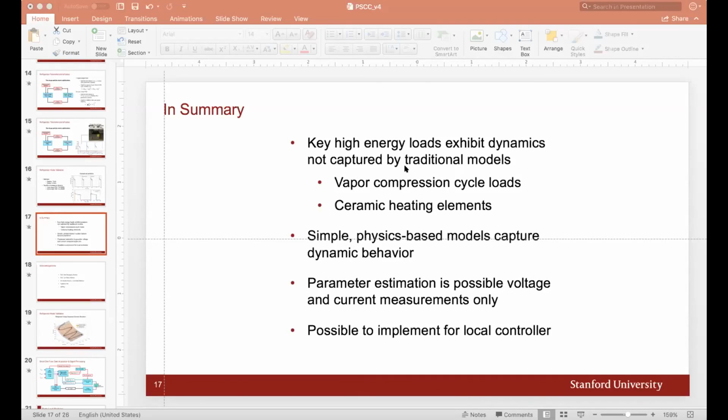Okay, last question here. Patrick asks, could you explain how you design the input signals and how you control the environment? Okay, that's also a good question. For the input signals, we just use sinusoidal RMS voltage excitations so we can look at the response in a frequency context, although it doesn't actually seem to matter too much whether you have a sine input or a square wave input. How do you control the environment? Okay, that's also a really good question, although I think we're running out of time here, so I might answer that offline.